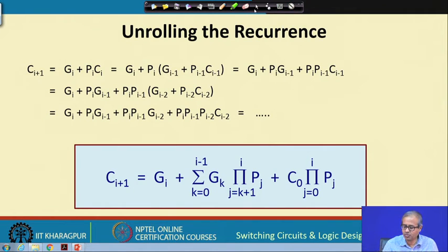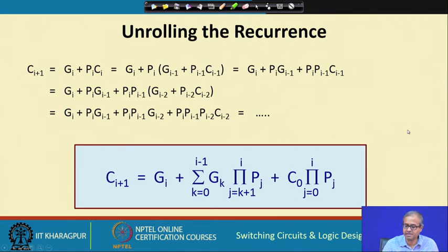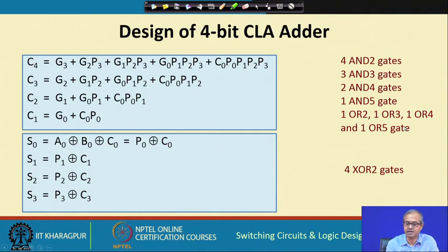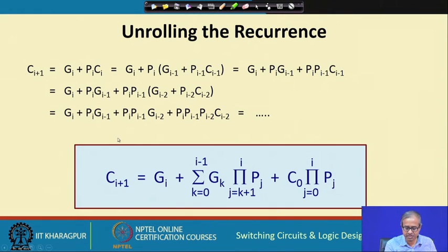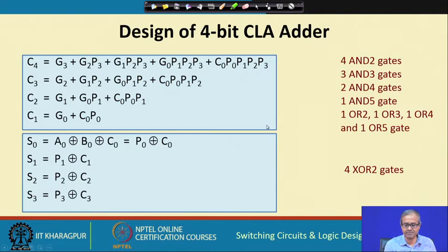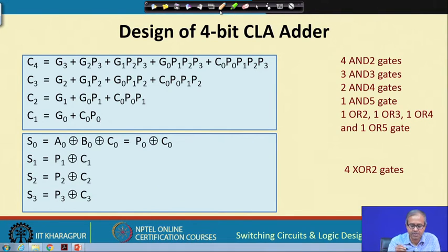What we want is that in terms of our design, suppose we are trying to design a 4-bit carry look-ahead adder. Just using these expressions that we have just talked about, we expand them the same way. I am looking from the reverse way. The first stage C1 can be written as G0 plus C0 P0.